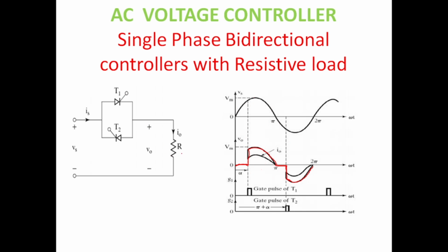So if you apply this voltage to an incandescent bulb, it gives you less light compared to the light emitted when you give the full supply. If the supply is 230 volt RMS, definitely the RMS value of this output is less than 230. How to calculate the RMS voltage for this waveform? That is our next job.